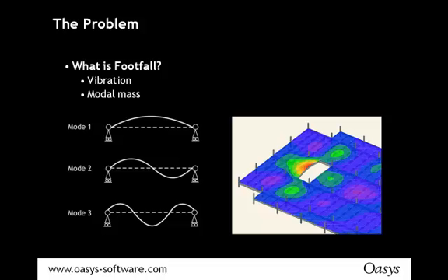Likewise, if you look at the frequencies, as you know, we need to do a structural analysis. The usual requirement is to have a minimum frequency on the floor for the fundamental, but this is only in the first stage, because a large floor or a large span can have quite a low natural frequency, but it has a large modal mass, so it can resist a footfall. Likewise, a short span can have a high frequency, but with a low modal mass can have a high footfall response. So there's not a direct relationship between frequency and response. It's quite a complex interaction.